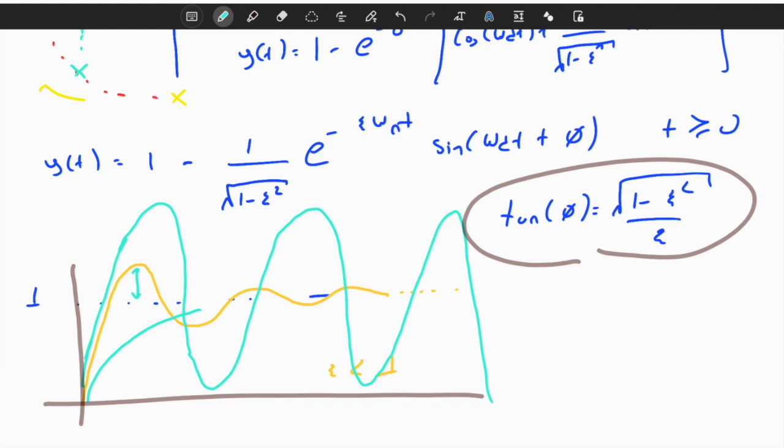Obtaining underdamped, oscillatory behavior in control systems is very possible if you don't adjust your controller and your system nicely, because it's related to the amount of damping of the system, which means that the level of damping or energy dissipation is not enough if you obtain this kind of behavior. So we know that if I increase the damping, from 0 to 1, I will approach the critical damped case, so it will have a good effect, and I will decrease this overshoot.